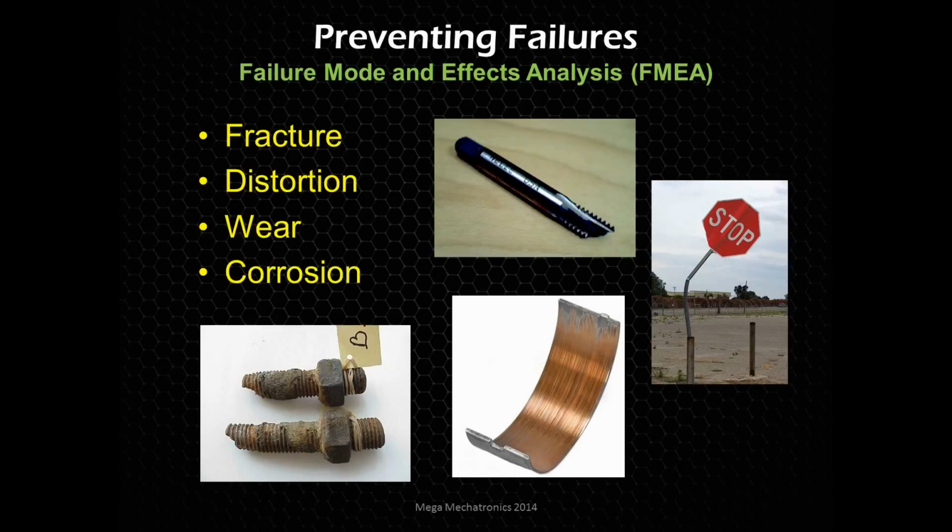And that's how you can improve your systems, by analyzing these failures and even analyzing it before you produce it. You want to understand the failure modes. How could this part that I designed possibly fail? And what are the effects if it fails? If this part bends, will that be a safety concern? If this part breaks, what's going to happen? Will the operator be injured? So you need to think of those before or as you're designing it, so you could sort of foresee the effects of that failure.